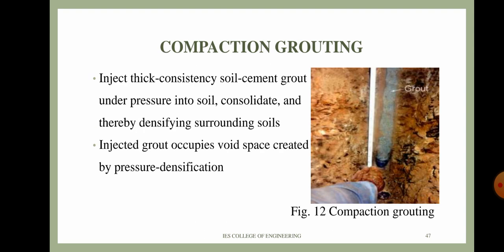And moving on to compaction grouting. In this grouting technique, we are injecting a thick consistency soil cement grout under high pressure into the soil, which consolidates and thereby densifies the surrounding soils. The injected grout occupies void space created by the pressure densification, and the figure shows the grout.